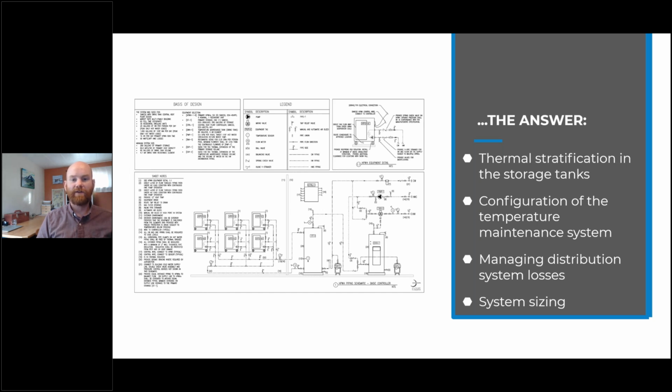Oversizing can present issues with these commercial heat pump water heating systems. And I've seen a few of those in the field over the past 8 years, where essentially it's one large heat pump water heater treating the entire load. And there's some issues with the sizing and the cycling of that system.